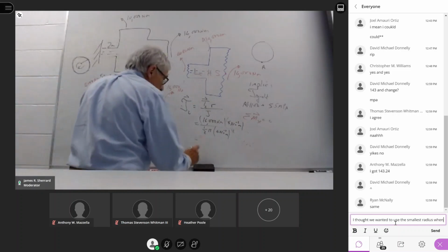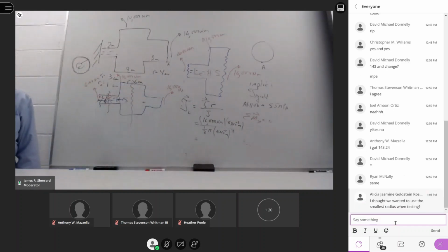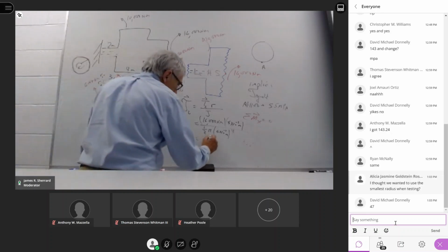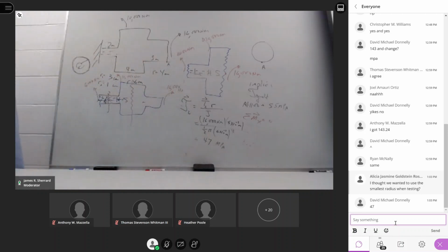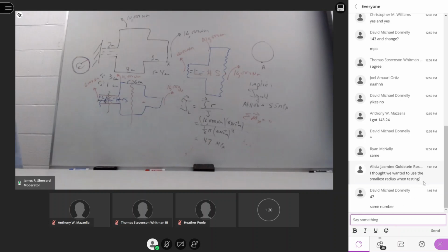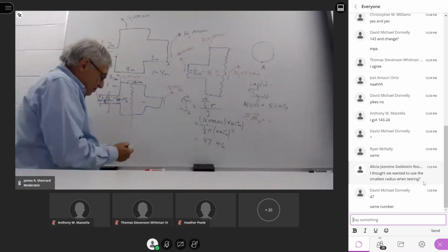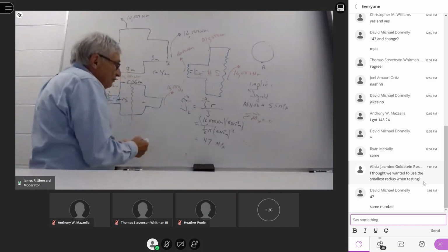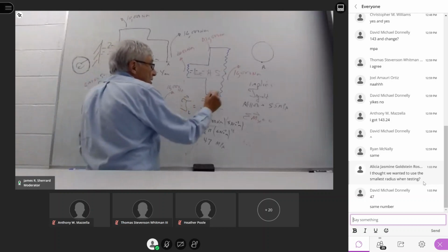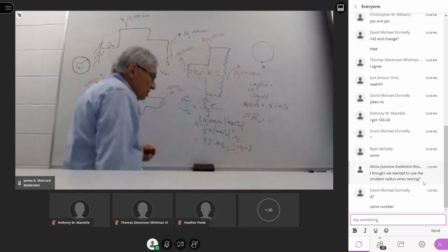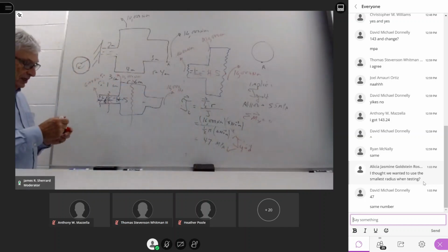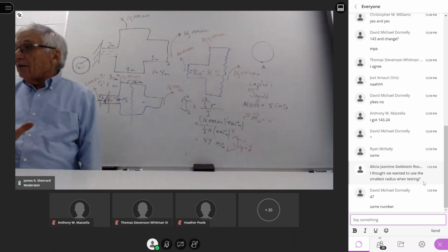Again, I don't have my answer with me. Off the top of my head, I want to say that was like 47 megapascals. Somebody let me know. What did you get? Same number, okay. So this is the value we got for region 2. We're again comparing this back to the yield value. So this is safe. So my middle region is safe. Any questions on that?